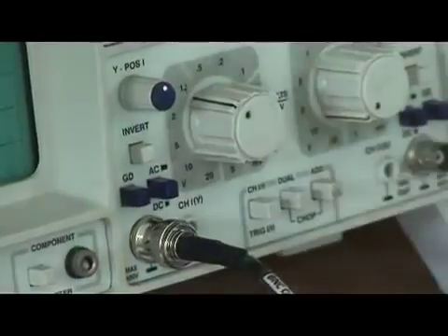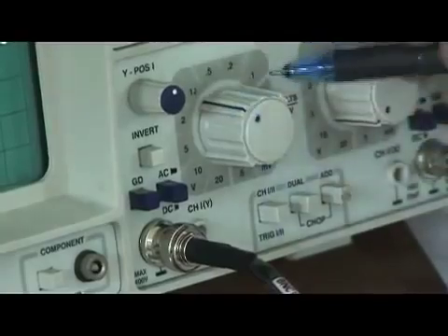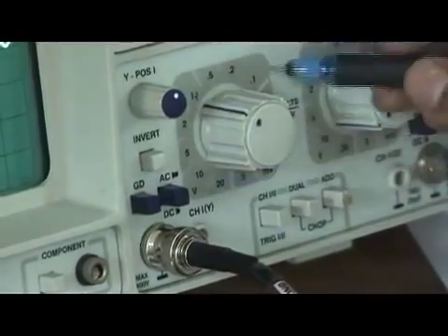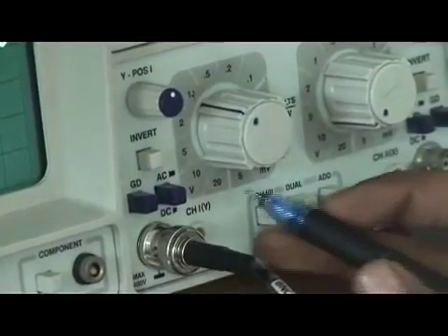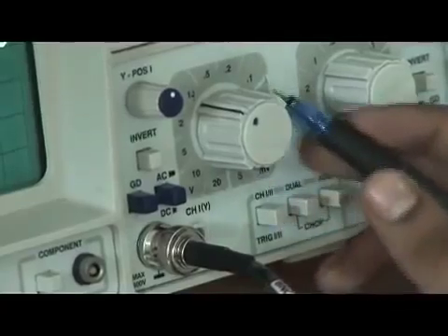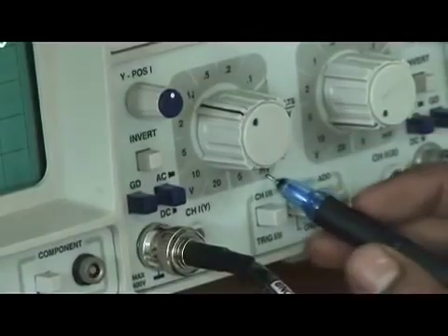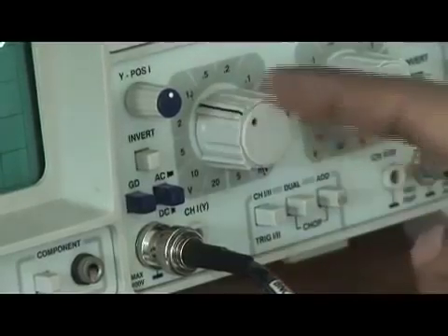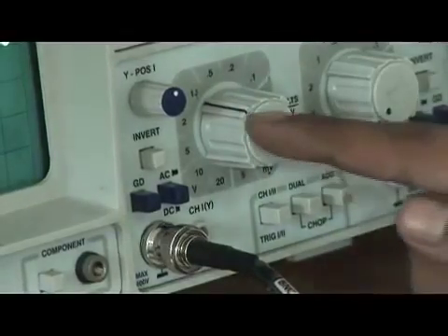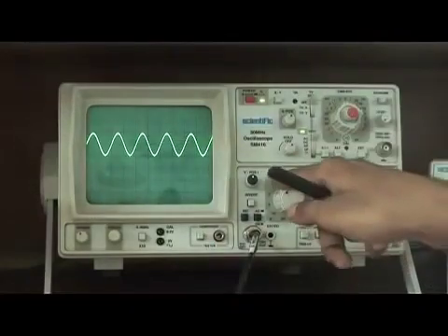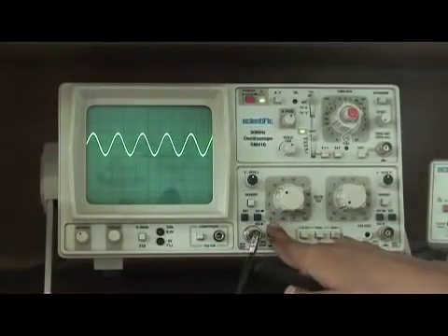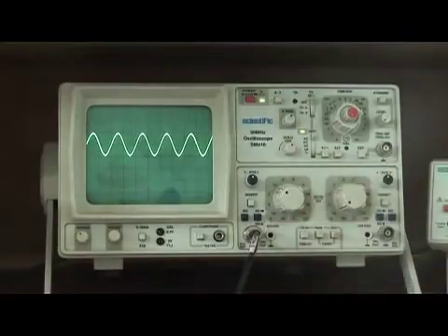You can see from this gap till this gap, there is no other unit except some numerical values. There is only one unit called V, meaning volts. From this gap to this gap, there are various numerical values, but there is one unit called millivolts. So whenever this knob lies in this range, the unit will be millivolt. When this knob lies in this range, the unit will be volts. So 1.9 blocks into 1 is 1.9 volts. We were generating a signal with an amplitude of 2 volts.